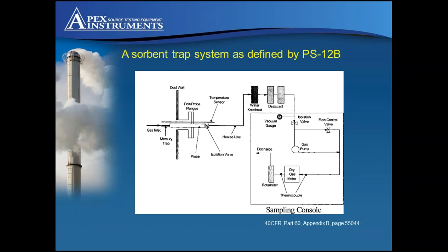PS12B also states that sampling must be performed proportionally to the stack flow. This is simply taking a flow signal from a source monitor, feeding it into the system, and controlling the sample flow. We'll talk more about proportional sampling a little bit later.